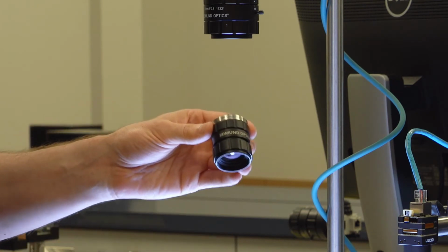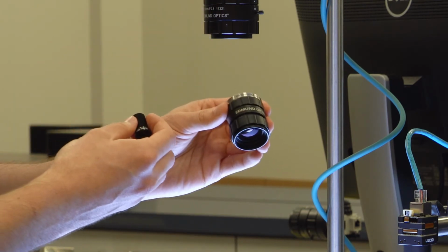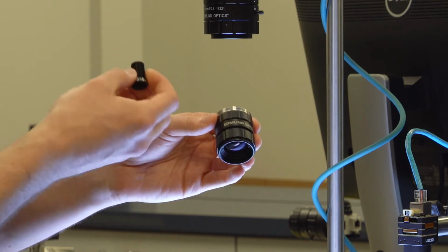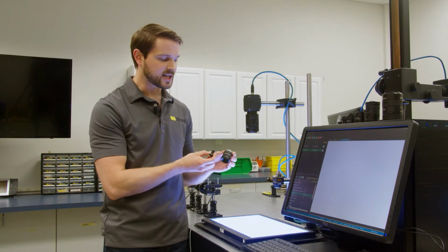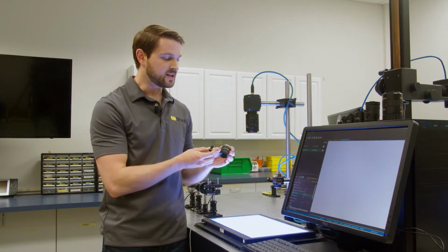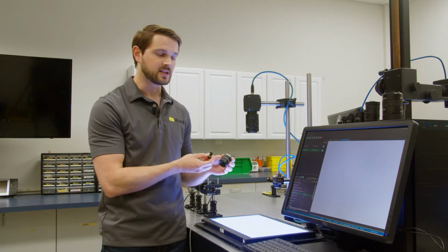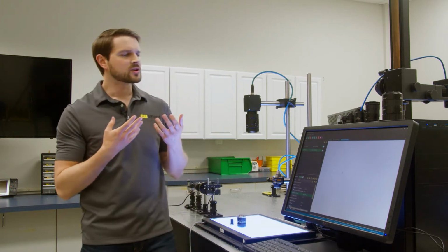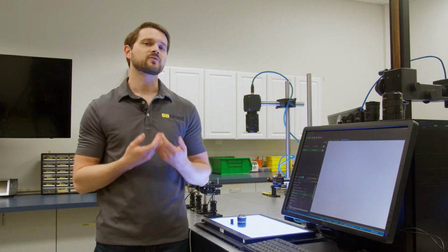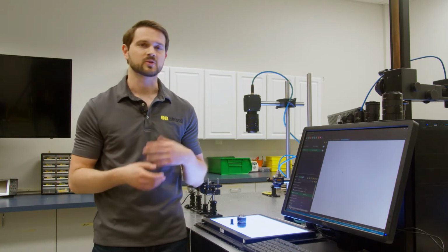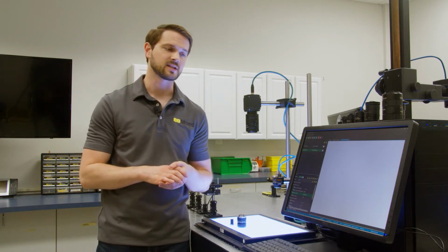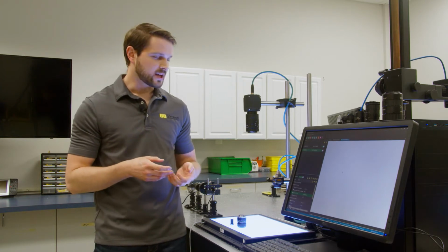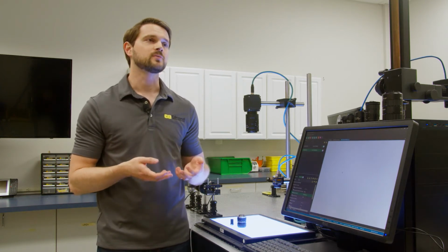That's the big difference between these two lenses: this lens here is designed for a 2/3 inch sensor, and the small M12 lens is designed for a 1/2 inch sensor. And it's really the design of the sensor size that determines the size of this lens, and one of the reasons why they're so differently sized. So if you're going to pair that lens with a particular camera, that's one of the first specifications you'll want to look at, aside of course from its resolution and distortion specifications: can it actually cover my camera?